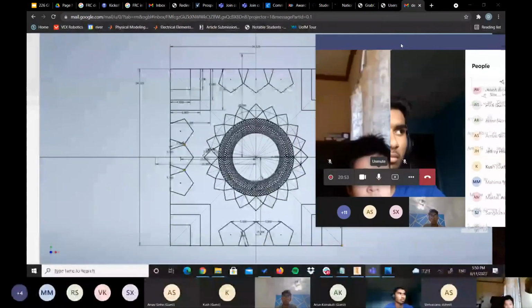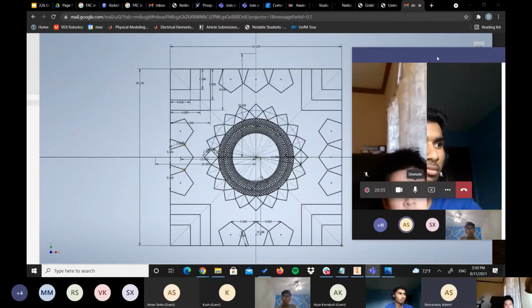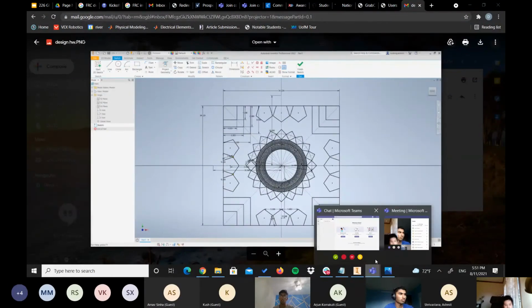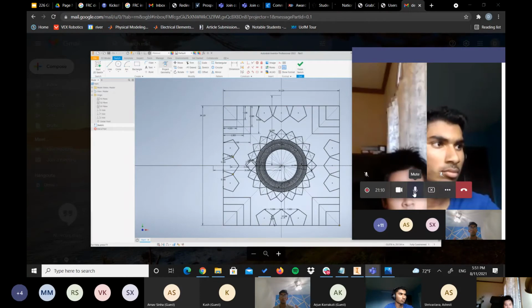Yeah. Okay. I just made the boxes and reflected them, and that's basically it. Good. One thing I wanted to point out for all of you who sent it to me: your sketches were all black, which is a good thing. If your sketches are not completely constrained, they will not be black, so your drawing is not done yet. So great that everyone got it.